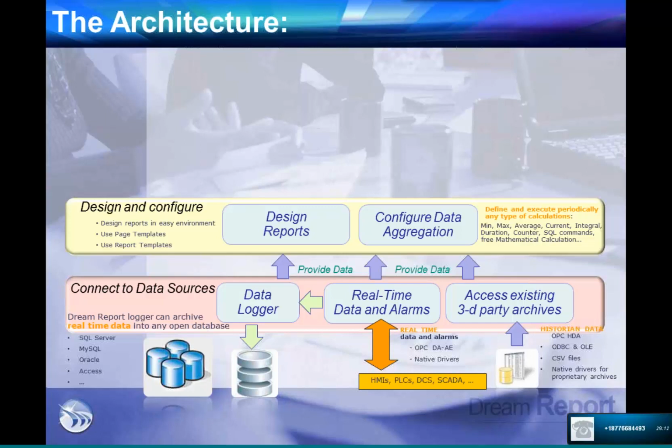For example, counter. Counter is a function that allows you to calculate consumption: to take the first value in the period, the last value, and deduct the first one from the last one, and like this we will be able to calculate the consumption. All you need to do in that case is specify the tags that correspond to the counter and the time period for which you would like to calculate the consumption.